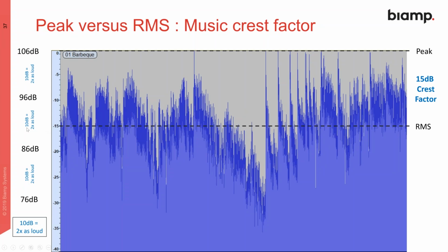So you can determine then, is that loud enough for the performance space that you're in? You've got a couple of options at that point. You could choose a louder or more powerful amplifier, a speaker with higher sensitivity, or you introduce delays. So if you're not getting the sound pressure level that you need at 50 feet, you can put a second set of speakers at 40 feet that are reinforcing and giving us more SPL.